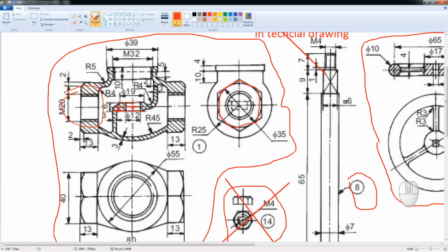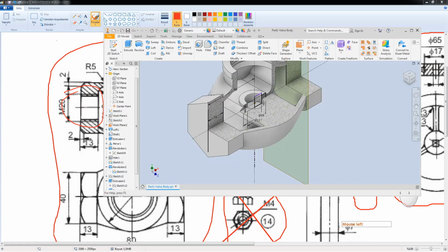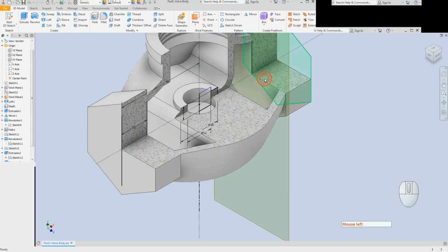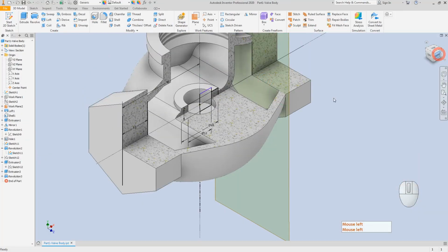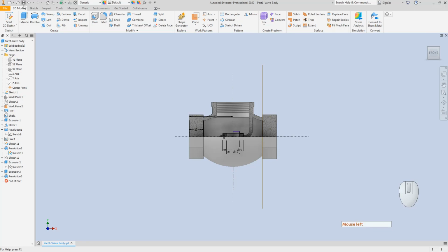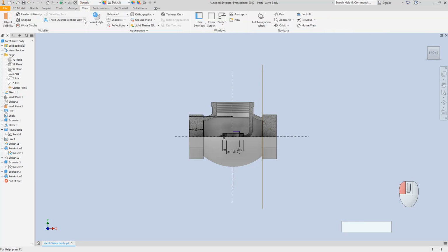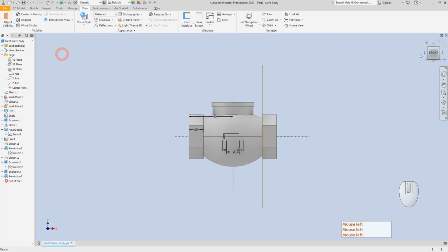I have the revolve tool this time. I'm just going to make an operation here. I'll just revolve cut by using this X. We just make an empty at this portion. We just made the part, our body part here. I will just save my part file.